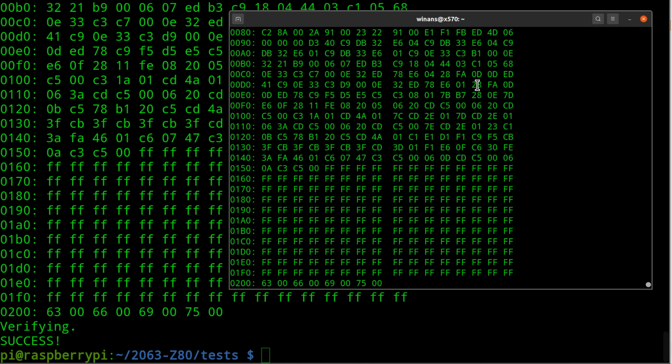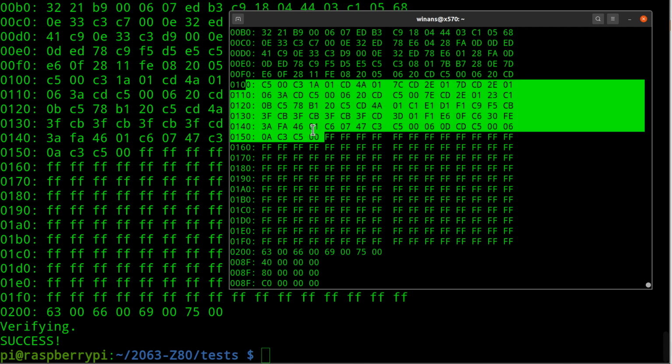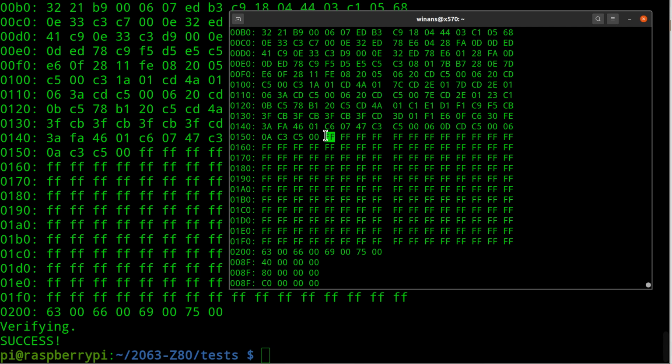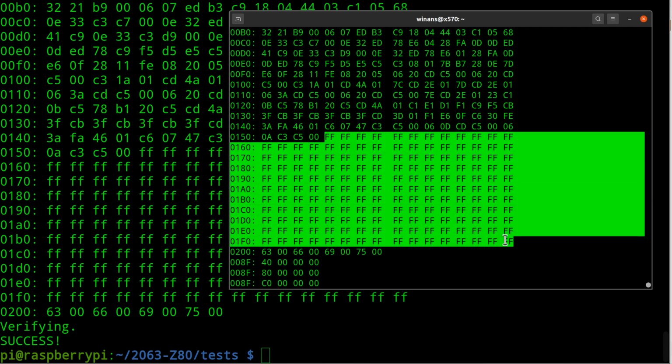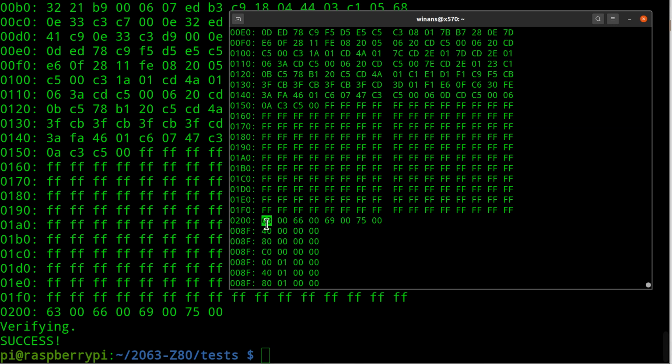So here's the hex dump of the program. We can look at the listing file, and we can see that this is all going to jive. Our code ended here, and this is the logic where I said, just fill up all the data with FFs until you have aligned the next instruction or the next data address to start at a multiple of hex 100, and 200 is an obvious multiple. And in there are our 1, 2, 3, and 4 pointers. This is our vector table right here, okay?